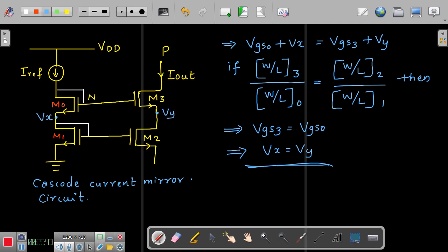See, whatever the variation that used to take place here, in our earlier diagram, we had VDS2 here. This was VDS1. So without the other transistors in our conventional current mirror circuit, even though VDS1 is equal to VGS1, which is equal to VGS2, your VDS2 was not equal to these values. So whatever the variations that you are going to have here would have prevented the entire circuit from copying the output current exactly as per the reference current, right? So that is when you consider the effect of channel length modulation.